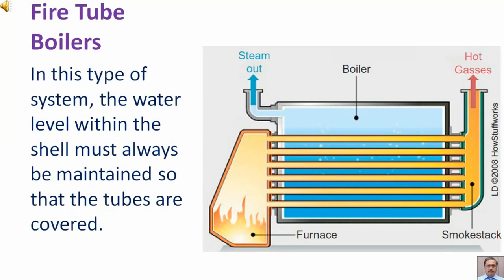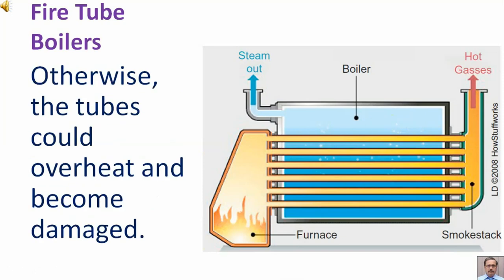In this type of system, the water level within the shell must always be maintained so that the tubes are covered. Otherwise, the tubes could overheat and become damaged.